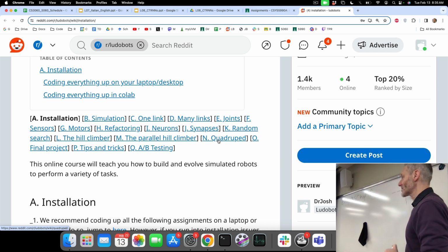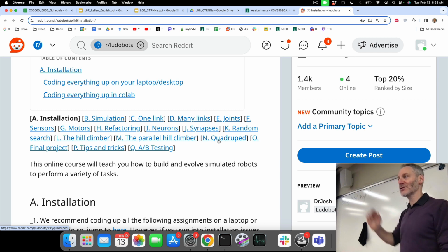And I suggest do not add all 9 links and joints at once. It's a little confusing. Add one link, one joint at a time. Make sure everything's working as you expect it to. Add another link, a joint, and on you go.